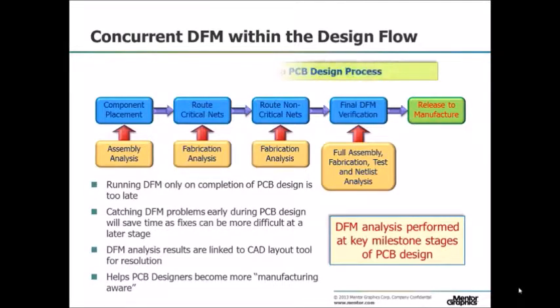So, running DFM on completion of design is normally too late. Catching DFM problems early during the PCB design will save a lot of time, as fixes are very much more difficult to correct at a later stage. The DFM analysis results are linked back to the CAD layout tool for resolution to make it very easy to find and modify the design to accommodate the DFM problems. Also, we find it helps PCB designers become more manufacturing aware so that they design with manufacturing in mind.